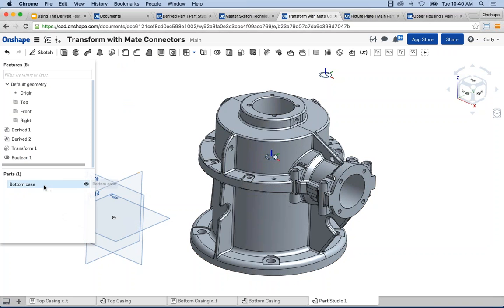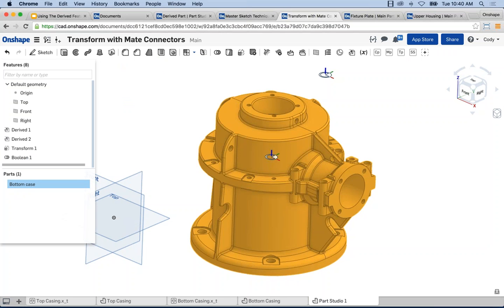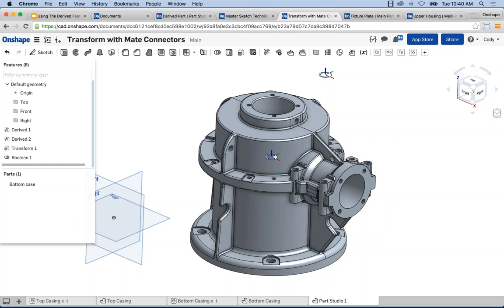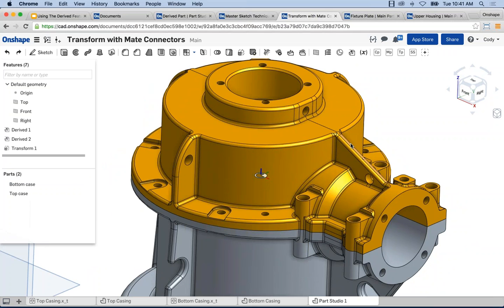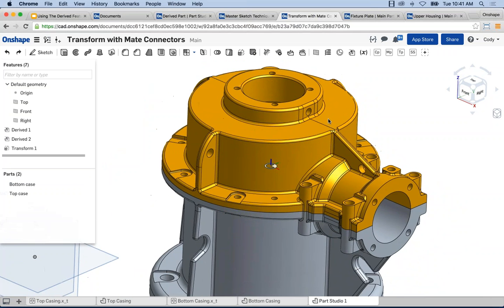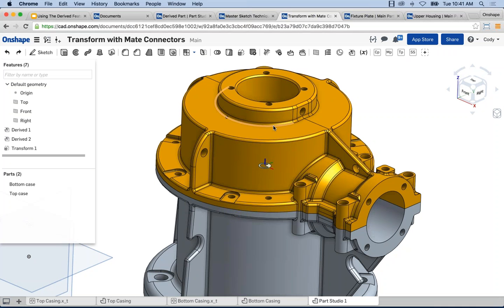Yeah, so now those are joined. So the answer is yes, and you can do that with extruded cuts, removes. You can add features to it, so it is not untouchable, so to speak. You can make changes to the derived feature, the model inserted in the derived feature downstream. And so now I can add another feature that ties it to a mount that I perhaps created or something. So lots of different things you can do with derived. It's not untouchable. Now, it's important to keep in mind if you want to edit what's here, you'll need to go back to the original.